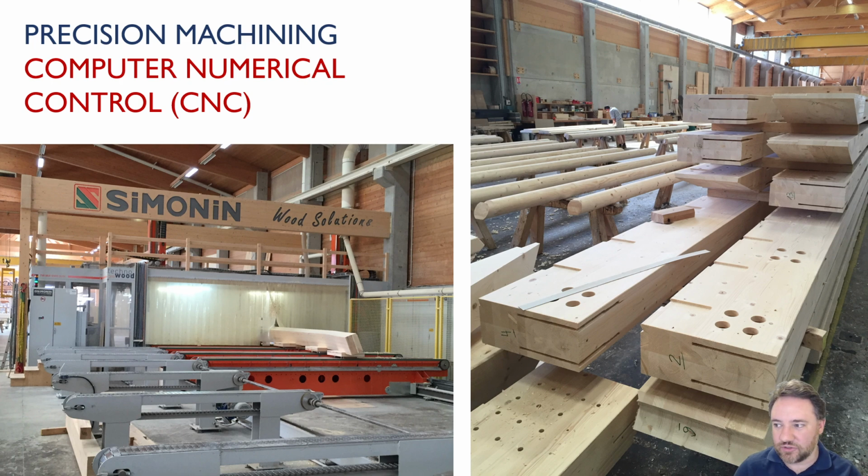And this is kind of a revolution in a sense for timber construction, because if I can use these heavy timber glulam or CLT and do all of the holes and slots and fit ups in the shop before I send them to site, then you get a really huge fabrication and construction advantage in terms of time. So it's basically just coming with pieces that we know already easily fit together, bringing them to site, and just bolting them all together, and not having to worry too much about the tolerances, because with machines like this, we can get probably sub 1 millimeter tolerance or something like that.